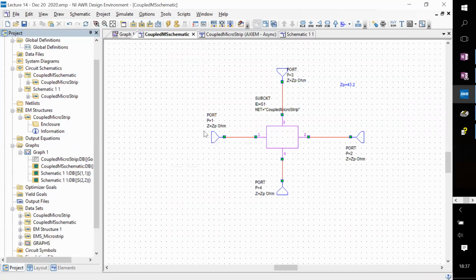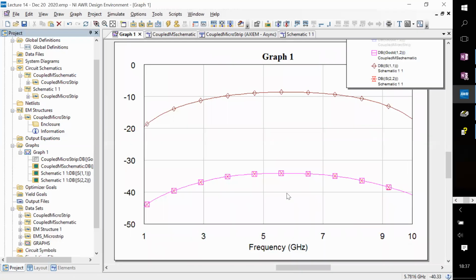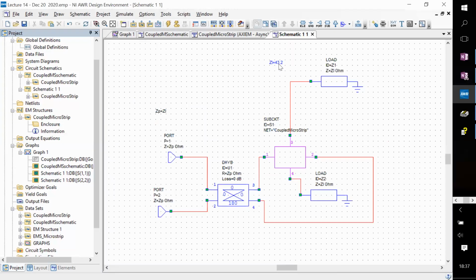It's close to 40 ohms. And what this is telling you is that the two techniques of measurement are in fact exactly identical, right? Remember, the pink is the odd mode impedance of that coupled microstrip circuit, but set up as a G odd measurement, whereas the red one is set up using this 180-degree hybrid and exactly matches. Now, because in this schematic there's only one port impedance and it's all the same, and we are measuring the even mode, but the parameters are set up to be odd mode, so it's not matching.